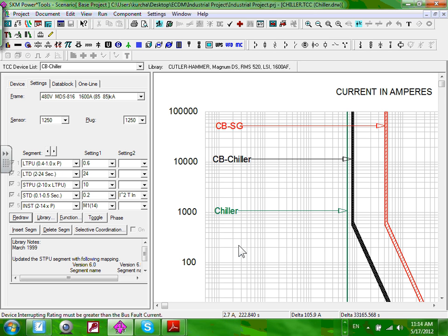So I actually can put, yes, it's 1250, but I can dial it down to 0.6. What's 0.6 of 1250? When you're saying 1250, are you saying the size of the overcurrent protection device? Yes, because we came up with like a 1200. But hold your horses. See how if you do coordination, you can get much lower than if you're doing it by the code.